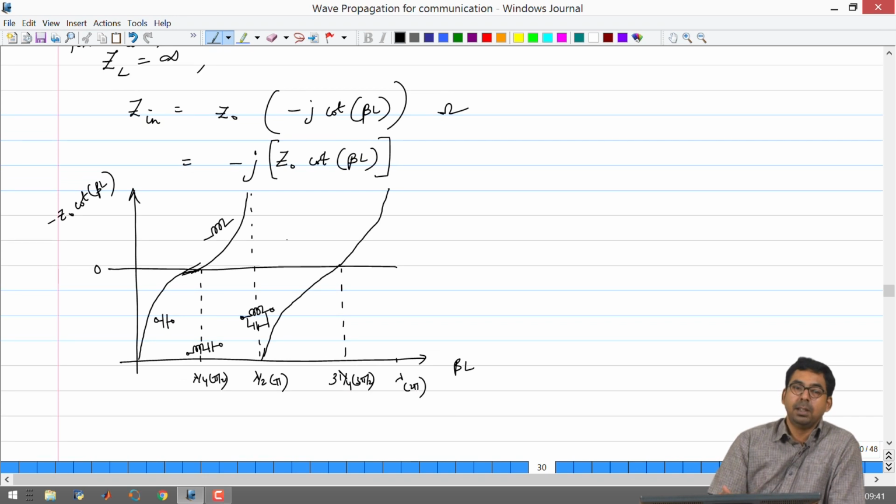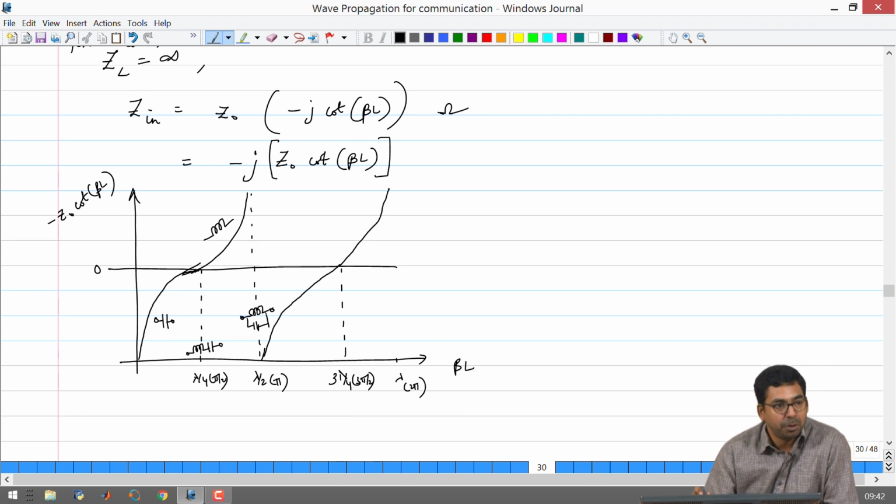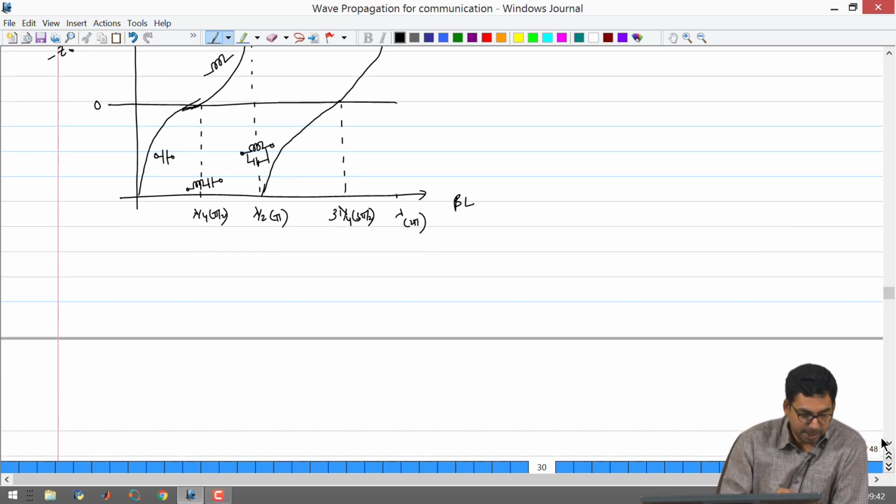So, it means that the technology for making inductor is not different from the technology for making capacitor. You will be making the same transmission line in your manufacturing company, but depending on the requirement for that particular case, you will be precisely dicing or cutting your transmission line to where you want, alright. So, it means that I can have LC and parallel combination of L and C. So, you could build a lot of circuits with this, alright, and all you will need is transmission line and cut with different sections.